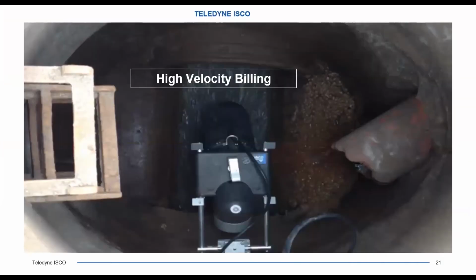Okay, here it is. Now, when we installed the laser in this application, you'll notice that you're not in the flow. It's an easy install for the most part. There's 2 bolts that hold it in. You'll notice there's a handle on the top. And what that's designed for is you can use a street level installation tool to remove and install that laser once you get it installed. The tabs on the mounting bracket are designed so that you can easily nestle that thing, or nest it back in place after you're done.